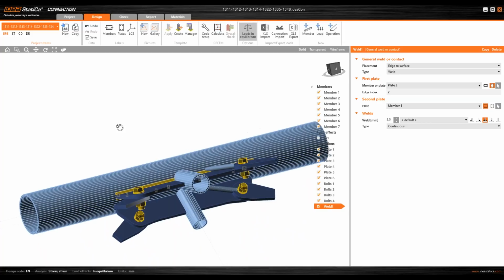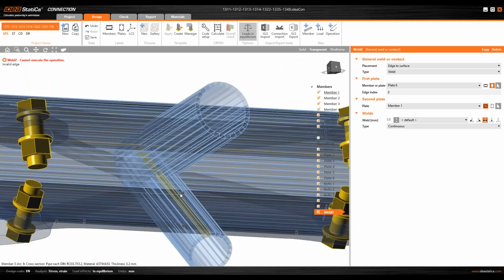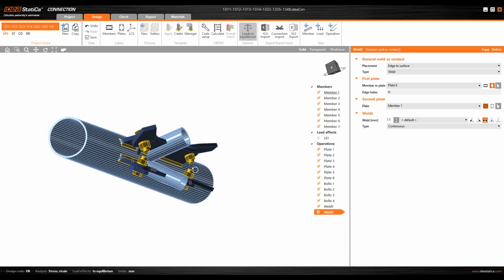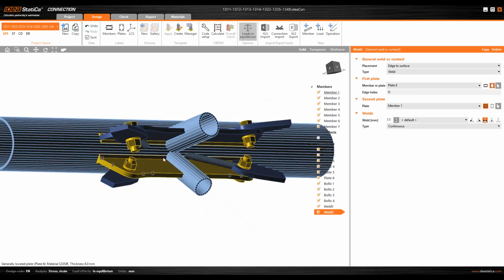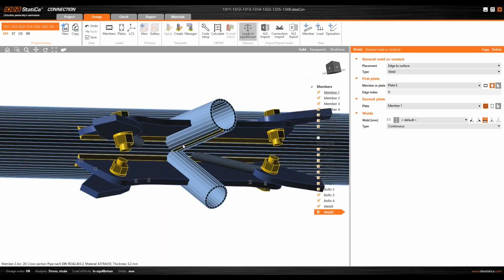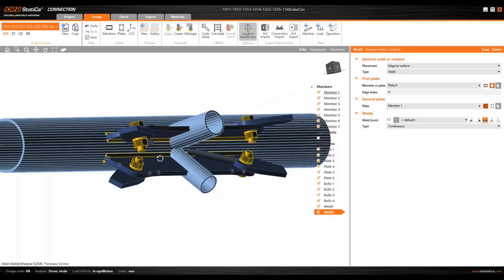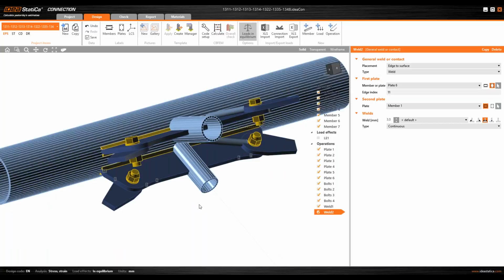Okay, now I'm copying this to the lower plate as well. Again, I'll just pick the edge number, which is 11 in this case. So this is somehow tricky. You can get a bit lost. We have to make sure that this number is well set. Otherwise, the model will not calculate or will calculate in a wrong way. So this is one important thing, always to check this edge number.